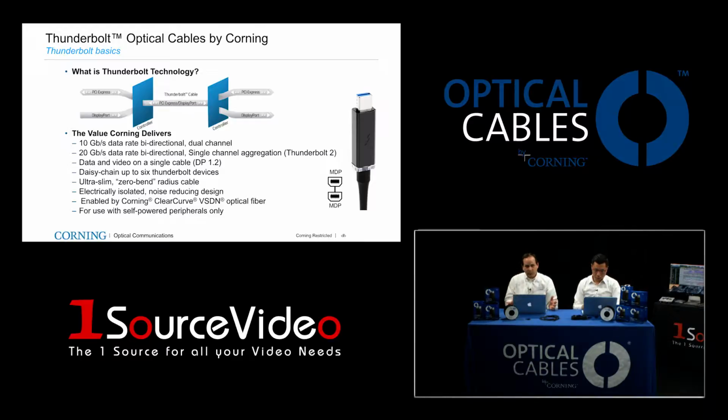We're DisplayPort 1.2 compatible. You can daisy chain Thunderbolt up to 6 devices over one chain, and you can do that with our Thunderbolt optical cables by Corning. We have a very small cable, specially designed, and I'll show you a little later how special it is. You can bend it to a 0 bend radius, which you can't do with any other product. It's enabled by a special Corning optical fiber, ClearCurve, that we use. It's 80 micron, and I'll get into more detail about that later. You can use our product with self-powered peripherals only, because it's an all-optical solution and it can't power peripherals.